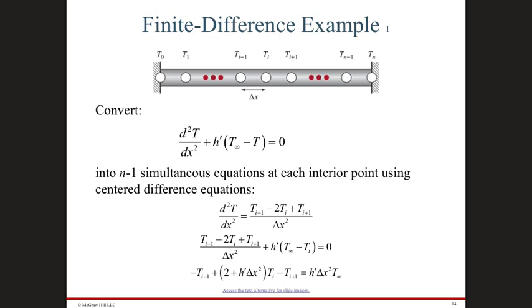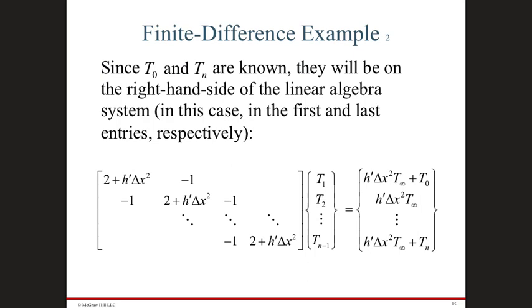So you reach T1000, which is supposed to be T at 10 meters. And that one is actually the 400 Kelvin given as a boundary condition. And we are talking about T at location 0, the start of the rod. That's the 300 Kelvin. So now you incorporate all your conditions, whether they are initial or boundary conditions. And then you start solving the set of linear equations that you have in order to figure out the temperature at every location.